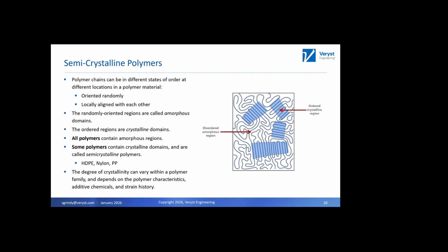Whereas in the polymer, it is never really going to approach that 100% crystallinity. And so you can imagine that in semi-crystalline polymers, those crystalline domains, those molecules are more tightly bound together. So that tends to do things like increase the strength and increase the stiffness of the polymer, just for example, because when those polymers are more tightly tied together, then it's more difficult for them to move.